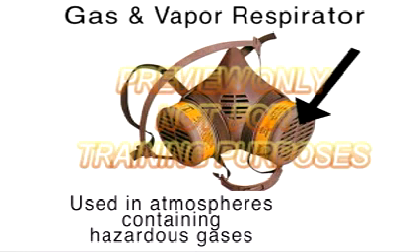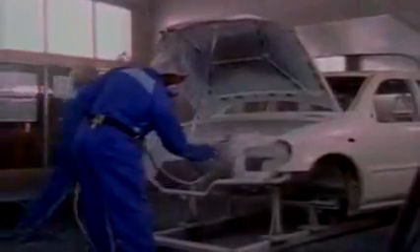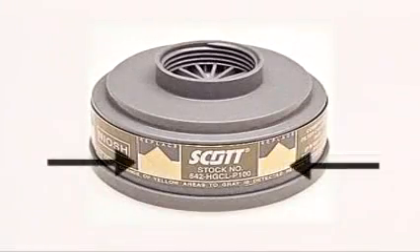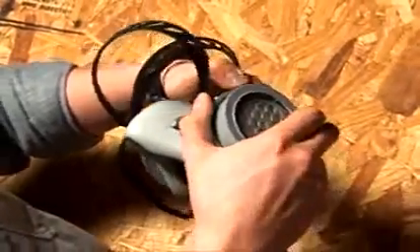These respirators use chemical filters, referred to as cartridges or canisters, to remove dangerous gases or vapors and protect against specific gases or vapors, not airborne particles. This type will provide protection only as long as the filter's absorbing capacity is not depleted. These are generally equipped with an End of Service Life Indicator, or ESLI, certified by NIOSH to warn a user of the approaching end of adequate respiratory protection. If no ESLI is present, a change schedule is necessary.